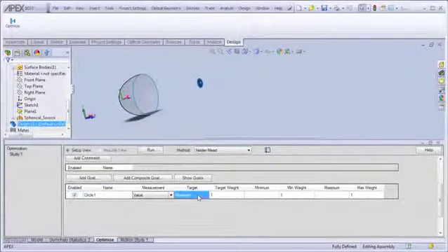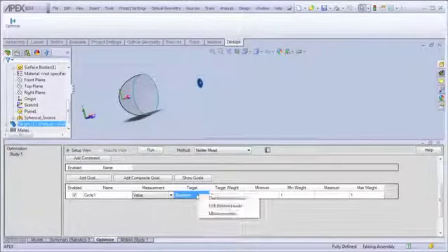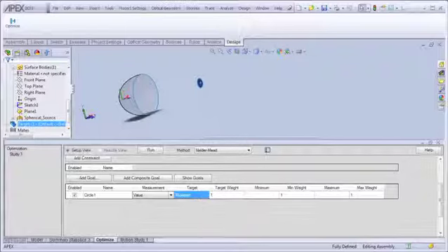Apex allows you to control the figure of merit depending upon the values that you enter for the target, weight, and the minimum and maximum values. If you enter a target value, you get the traditional center-seeking solution. For maximizing a value, if you right mouse click and choose maximizing a goal, Apex will attempt to maximize that particular parameter on the target that is specified. If you enter minimum and maximum values, you will force an edge-avoiding solution and configuration of the merit function. The minimum and maximum values are the edges to avoid during optimization.